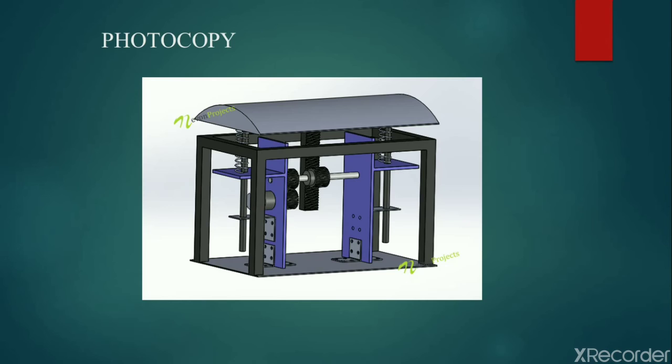And this is the photo of the smart speed breaker arrangement. If you see this photo, you will clearly understand the concept. This is the smart speed breaker, and both ends are connected by a spring. At the mid portion of the speed breaker, it is connected by a rack, and the pinion is directly meshed with the rack, and the pinion is placed on the shaft.